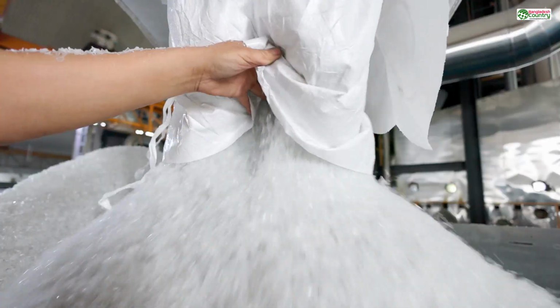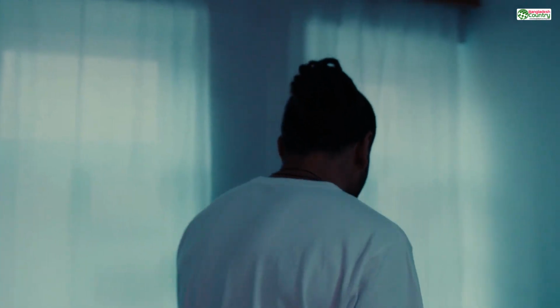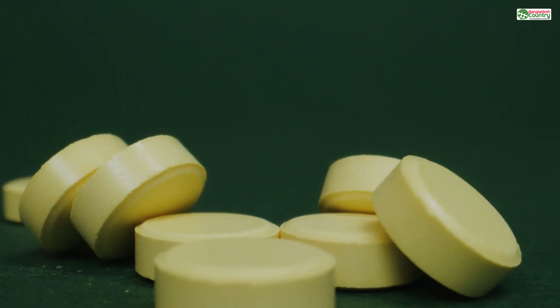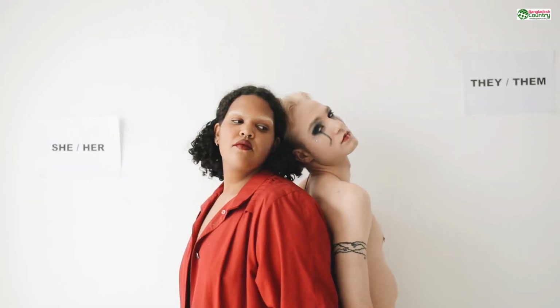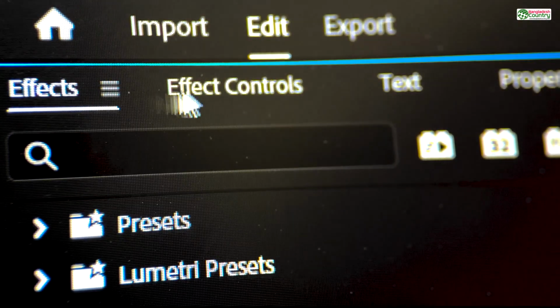For high-detail resins, you might get away with as little as 0.8 to 1 millimeter for decorative features, but again, check the guidelines. These aren't suggestions. They are the physical constraints of the machine and the material. Ignoring them is like arguing with gravity. You will lose.